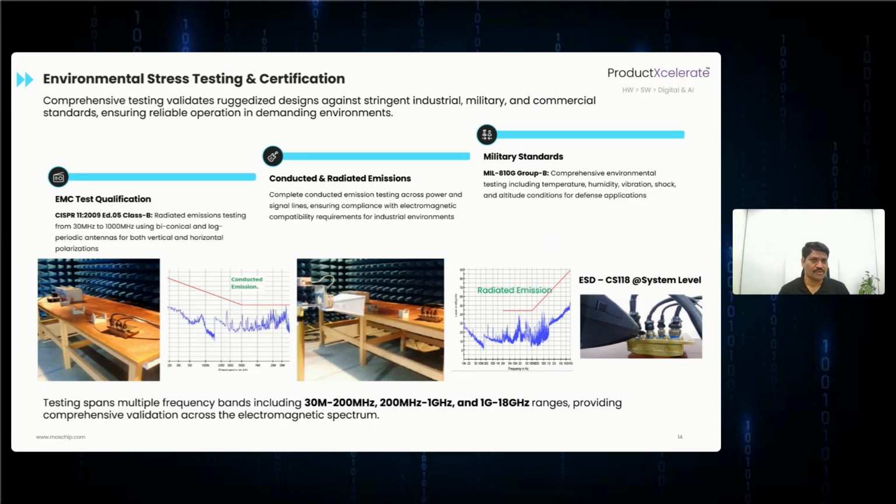So we push our systems through thermal cycling, humidity chambers, vibration rigs, high altitude, acceleration, damp test, salt corrosion, mold test, and shock test, post the conformal coating measures at product level, to make sure the end product is more rugged. It's about building confidence that once deployed, the product doesn't die in the wild. Certification becomes the stamp on engineering discipline.